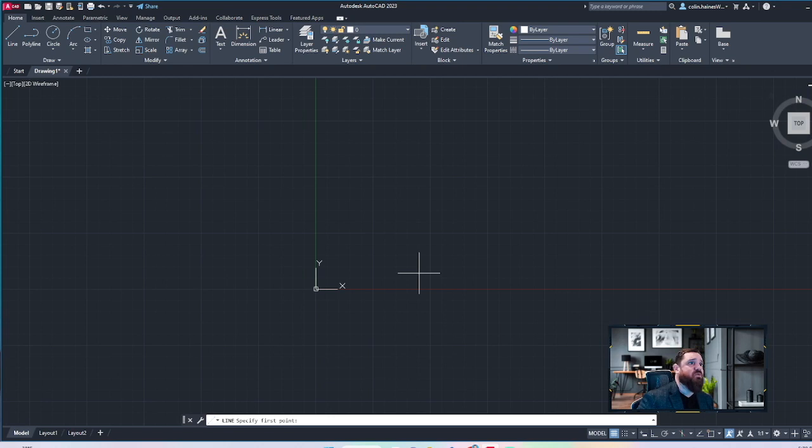So absolute coordinates, like if you type in 1,1, and then you type in 5,5, that's going to go to the grid coordinate 5,5. So it's essentially going to go over 4 on the X and up 4 on the Y. Relative coordinates, on the other hand, if you typed in 5,5 on relative coordinates, that is relative to the point you're using. So if we started at 1,1, that's actually going to go over 5 on the x-axis and up 5 on the y-axis. So the point you'll end up at is actually 6,6.